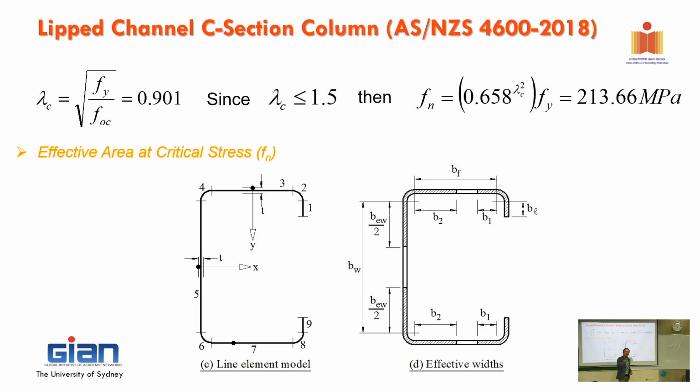And now we need to calculate the buckling capacity of the load. So we have stress. How are you going to calculate the load? That's right. Very important in here because the whole section is not working fully effectively. Then we need to calculate the area, the shadow area in here. We have to remove those what we call useless areas where it's not effective. So in our calculation now, we need to calculate AE. Of course, AE will be a lot smaller than A, the cross section, because we're going to remove that area. Okay? So that's what we're going to do next.